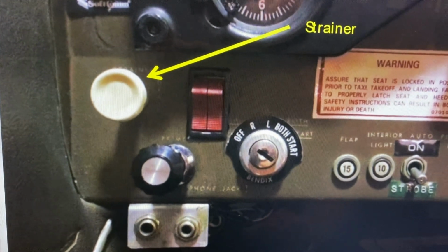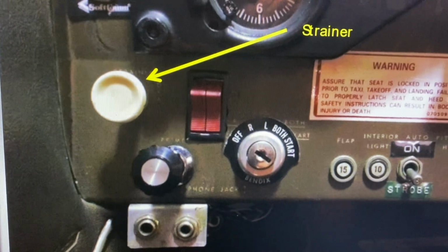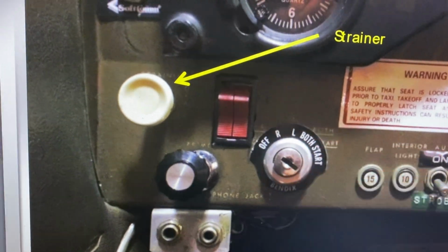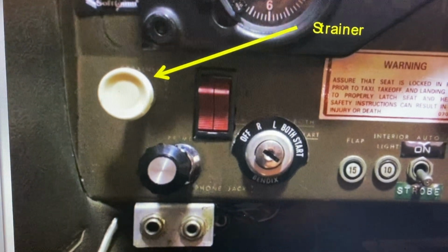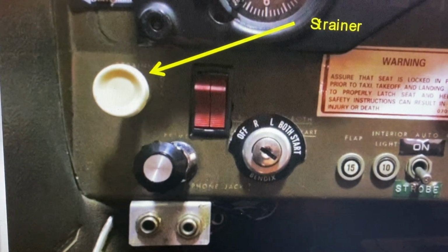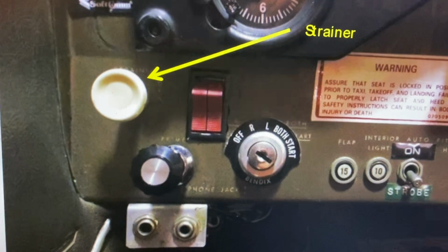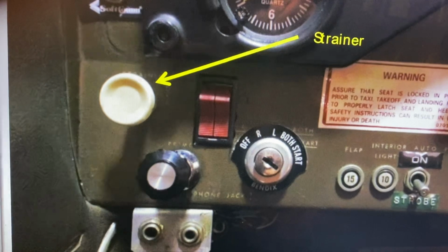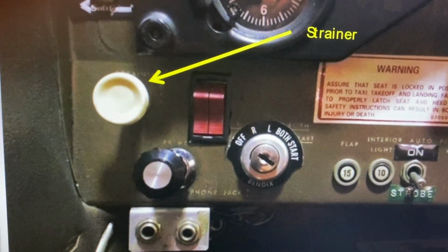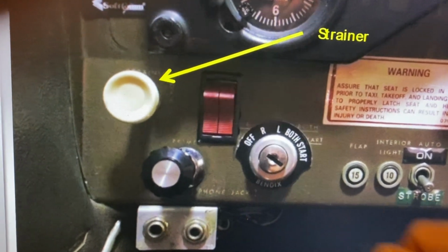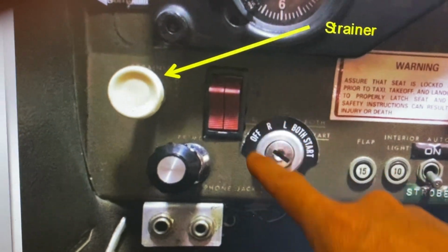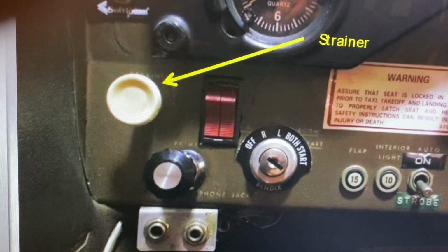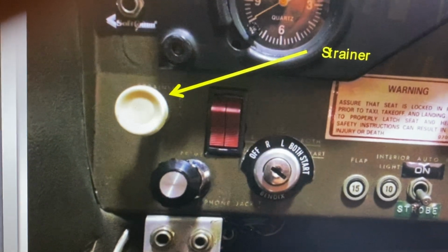And there is a specified RPM. It's usually around 100, 150 RPM you're supposed to lose. Then you go back to both, let the engine stabilize, and then you select the right mag and double check what its RPM drop is. And if its RPM drops within the legal parameters, then you go back to both, and that's called a mag check. If you were to ever go to off, the engine would shut off, but we don't shut engines down that way. I'm going to talk about how to shut the engine down here in a second. So that's called a mag check, and this is the magneto switch, also known as the ignition switch on this one because it's the same switch. The magneto switch: right, left, both, and start.